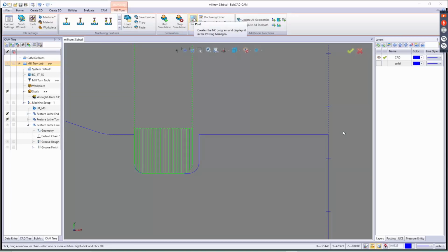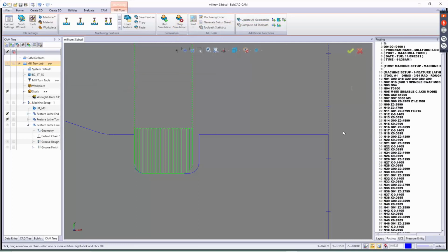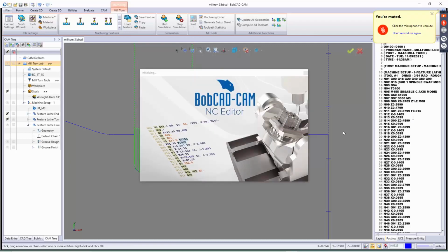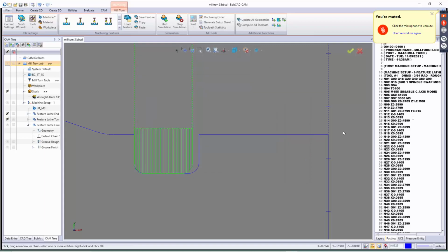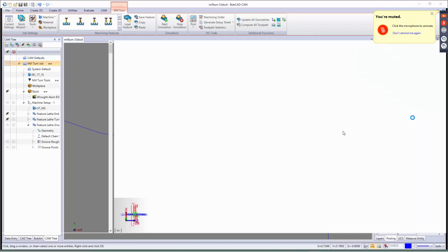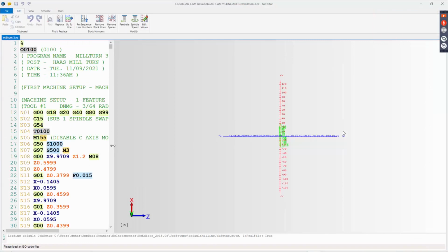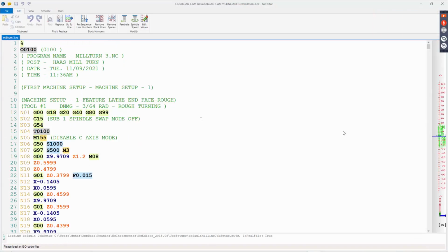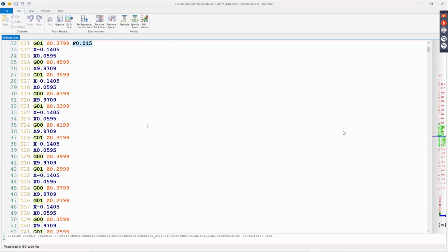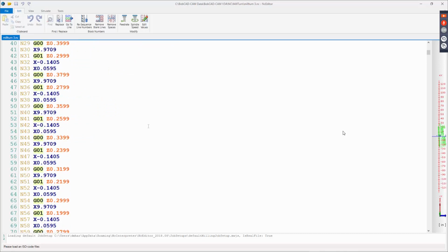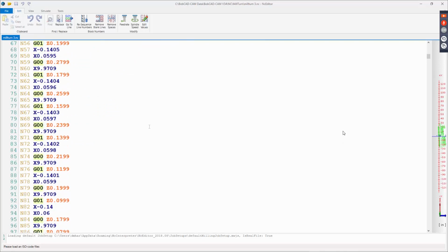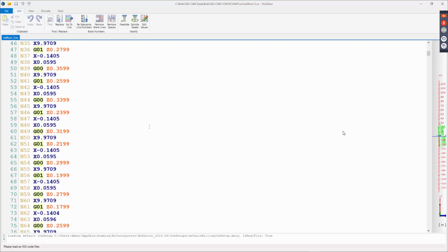Next thing I want to show you is your posting here. So hit Stop Simulation. Again, I'm looking at just the separate moves here. So, of course, the G-code is going to be a lot more. I'm not doing canned cycles at all, just so I have options in my parameters and patterns pages there. Yeah, we're not worried about this. And there's all your G-code pretty much for all this. Again, this is all separate moves on there.